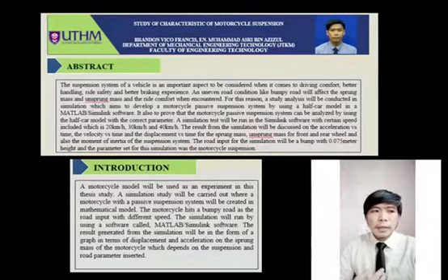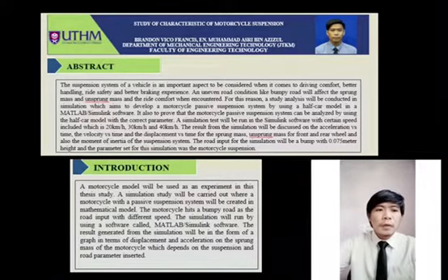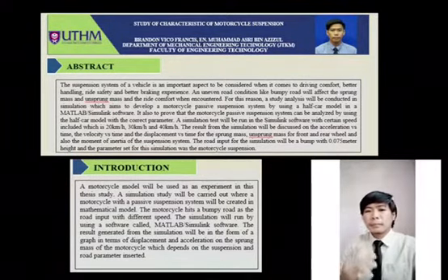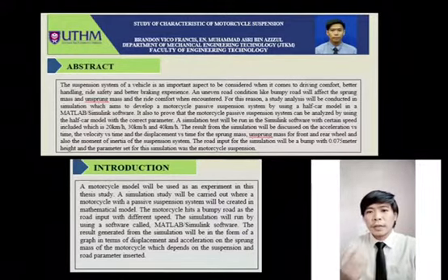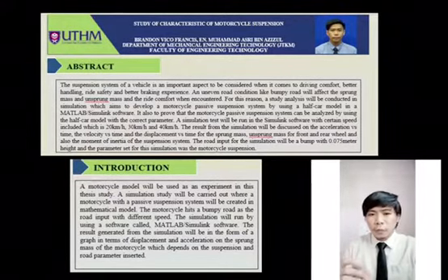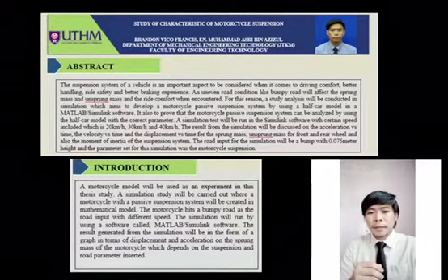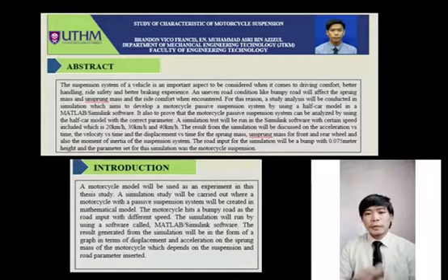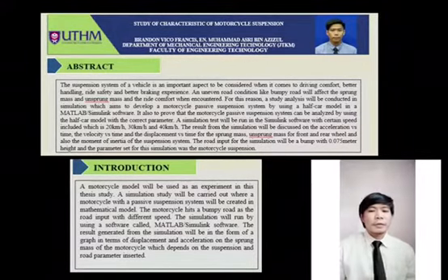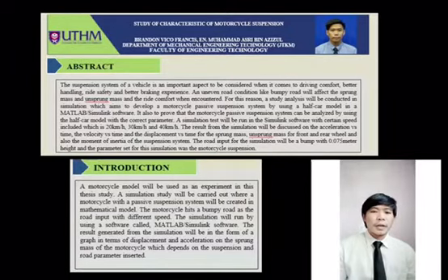So basically, the problem statement for this project would be when a motorcycle hits a bump, the bump will generate a vibrating force to the wheel, and then transfer the vibrating force to the passenger seats that affects the passenger driving comfort or ride comfort for the motorcycle. And not only that, it also affects the braking ability, the handling, as well as the safety of a vehicle when it comes to the suspension system traveling on the road, on a different profile of the road.